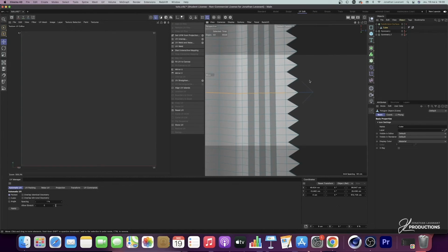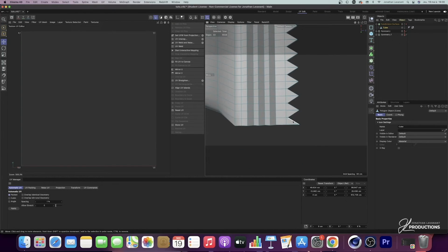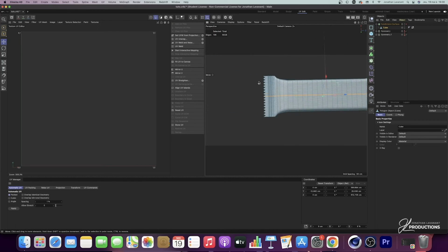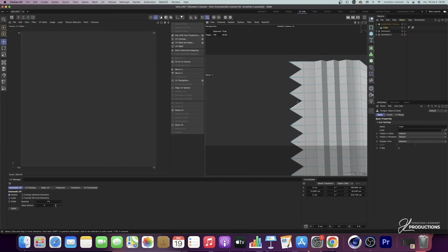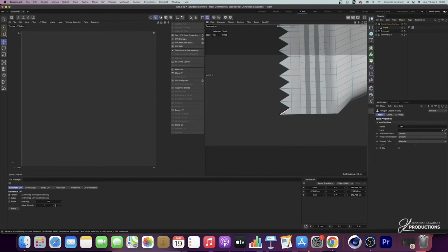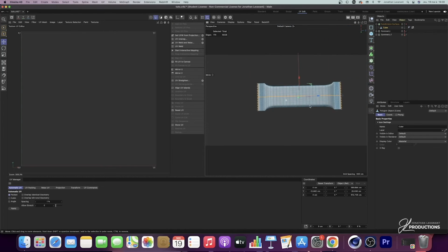So here I am going to create. I'm going to select the edge at this level. I'm going to the opposite here. I'm going to do Shift and Control to select all this side there. I'm going to do the same on the opposite. I'm going to zoom in on the edges. I selected that one. I'm going to the opposite here. I'm going to do Shift and Control. And suddenly we will have our cuts at the level of the orange lines.